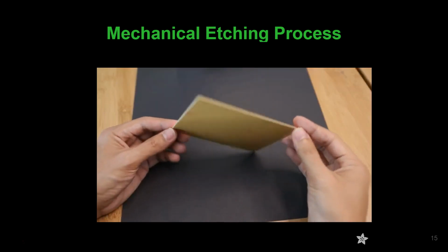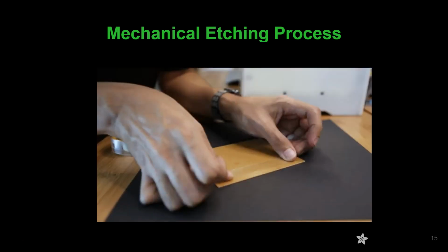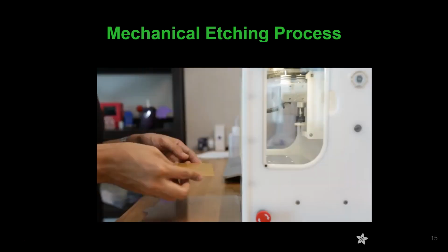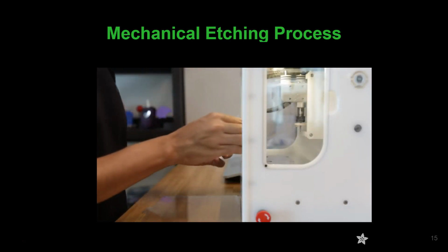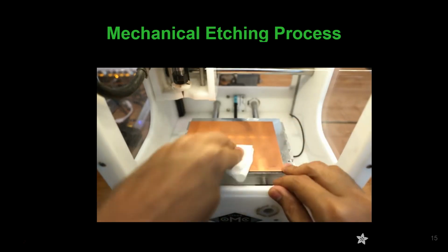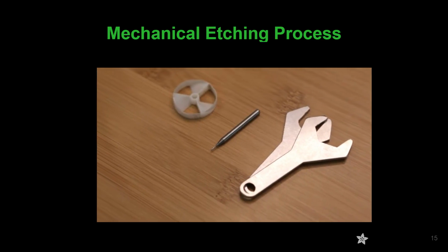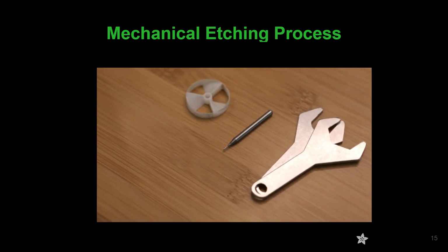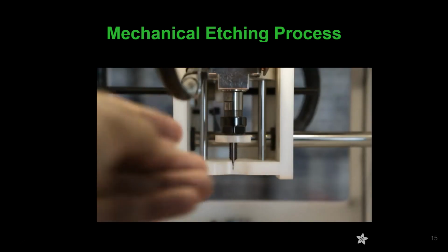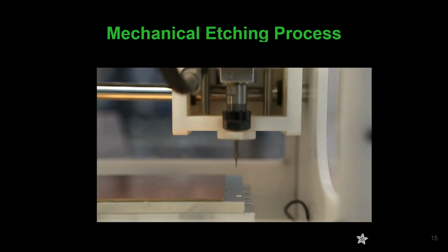Once all of the exposed areas are all bright and shiny, totally free of resist, we can pull the board out and give it a quick rinse in cold water. At this point, you could scrape away any unwanted resist or fill in any holes that you spot with a fine point permanent marker. If everything looks good, then it's time to move on to the etching.